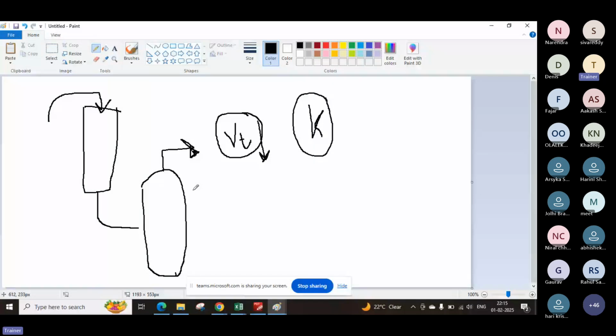When you have a falling film evaporator, generally evaporator means a higher percentage of liquid is being converted into vapor. So your liquid level at the inlet is minimum. That's why it should be a vertical separator only. So in this condition also we should calculate low liquid level and everything. Obviously, unless and until, I'll tell you some examples.